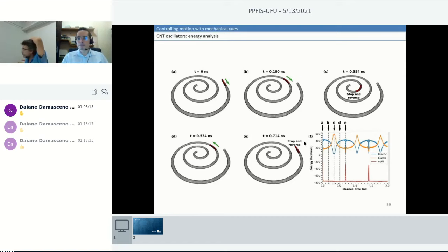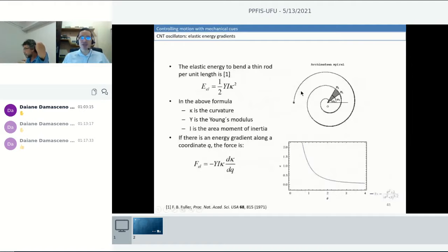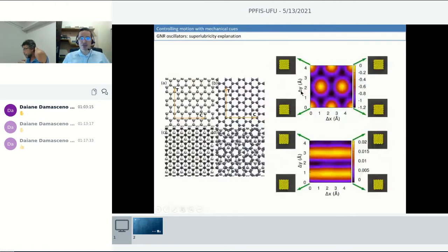Yeah, but this friction is related to the van der Waals interaction, right? Yes. But once the tube moves inside, if you get a very smooth potential energy, essentially the van der Waals energy is constant. So it's high, but it's constant, and it won't really try to stop the motion.